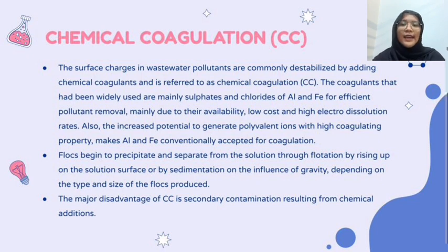The coagulants that have been widely used are mainly sulfates and chlorides of Al and Fe for efficient pollutant removal, mainly due to the availability, low cost, and high electrodissolution rates. Also, the increased potential to generate polyvalent ions with high coagulating property makes Al and Fe conventionally accepted for coagulation. The generation of polyvalent ions Al3+, Fe2+, and Fe3+ from the coagulant dissociation in the solution is followed by